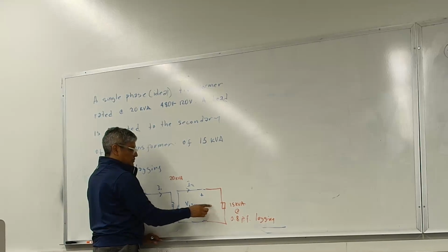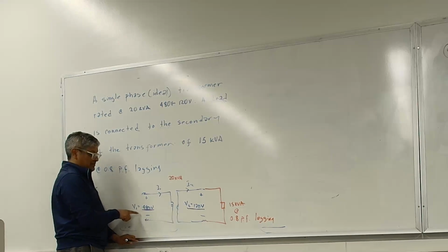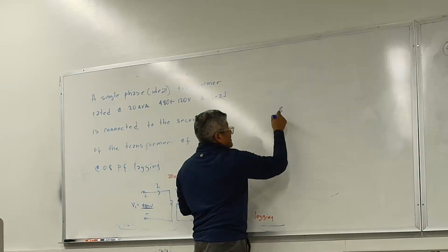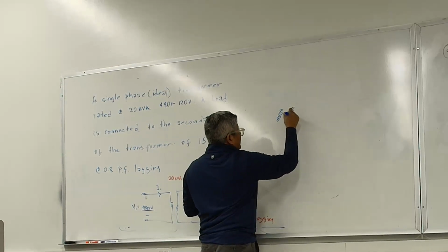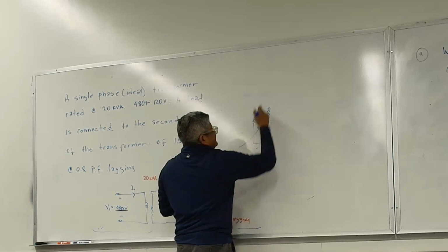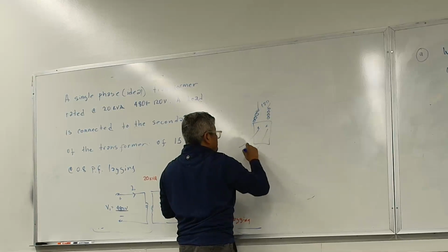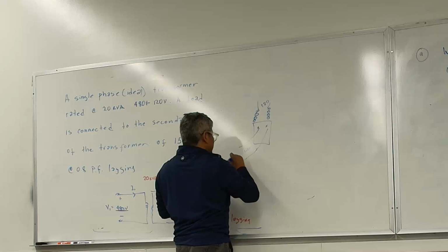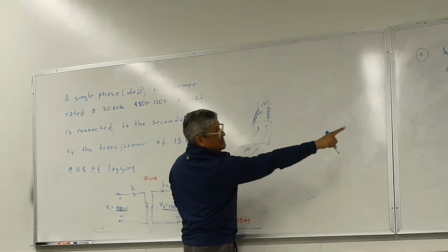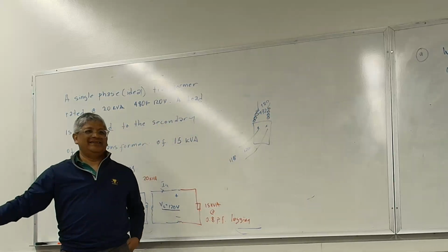118 volts, okay? What is the utility side voltage of this transformer? This is not a good example, but let me try it anyway. Say, for instance, you have 480 volts rated, 120 volts rated, but when this is 118, what is the voltage here? Basically, it's 472, right? 472. That's what it's running on.